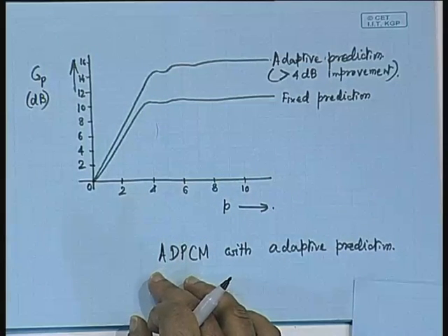But again, if you look at the short time autocorrelation values, you will see that beyond j equal to 3 or 4, there will be a sharp dip in the autocorrelation value. But the autocorrelation value will again attain some peak at its periodicity interval, right. Remember, speech signal is quasi-periodic.